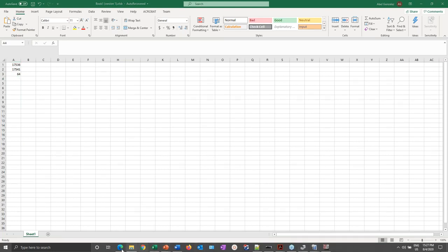Now, in RTMS, whenever we read the settings, we're reading the settings of the active group that's enabled in the relay at that point in time. Let's say, for example, you have active group number 1, and that's your normal everyday settings. Then you might have storm settings, so if you have a storm or some weather coming in the area and you want to switch to an alternative setting group, you can test both groups.